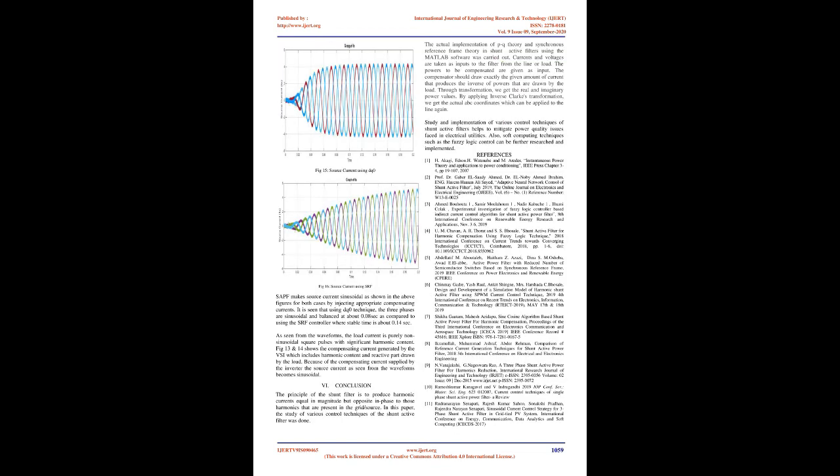3-phase inverter block. The switches used in the simulation are IGBT switches. The output of the inverter is fed back to the input of the SPWM block for minimizing the error. Switches of the same leg are operated in a complementary manner, hence NOT gates are used, shown in Fig. 11. The 3-phase output from the inverter is injected into the system through a coupling inductor. The coupling inductor helps to suppress the high-frequency components generated in the output due to the switching action of the switches.